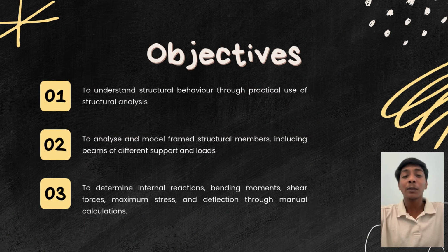Objective. There are three main objectives. The first one is to understand structural behavior through the practical use of structural analysis. The second one is to analyze and model framed structural members, including beams of different supports and loads. The last one is to determine internal reactions, bending moment, shear force, and maximum stress and deflection through manual calculation.